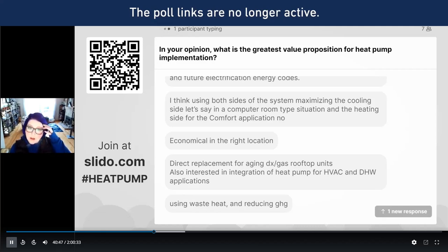I just went to a webinar about the new Sanco 2 cold climate heat pump that was announced, and the change in it was actually at the bottom of the drain pan. They put in a heating coil, so now when condensation happens and it drips down to the bottom of the pan, there's a heating coil, a little bit of energy that's sacrificed, that keeps that water from refreezing and stalling up the coils.